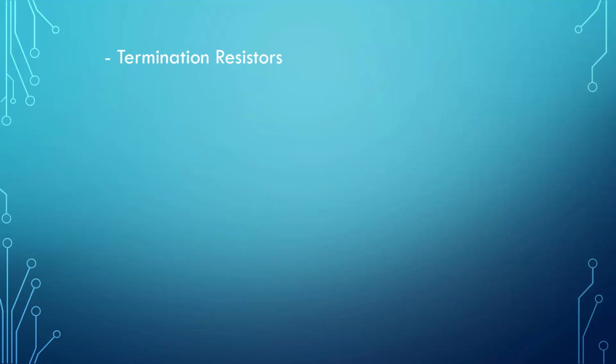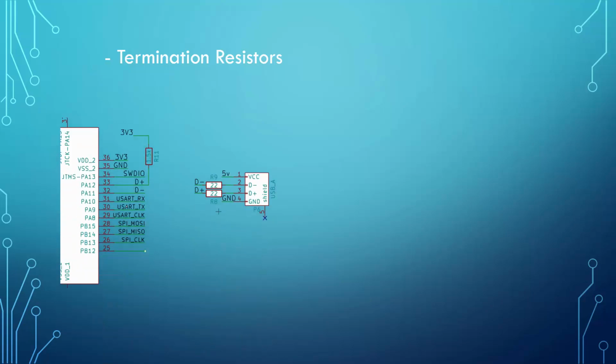In some cases, they are used as series termination resistors. These resistors are recommended only in the case of very high frequency communication or when the communication line traces are over a large trace distance. You usually see them in high-speed microcontroller or microprocessor circuits with high frequency signals. For example, in this circuit, R8 and R9 resistors on D plus and D minus pins are series termination resistors.